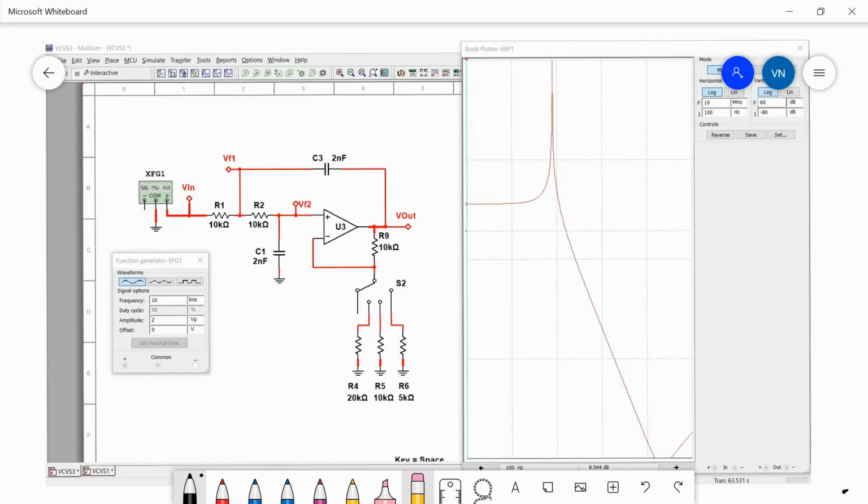Now, there isn't going to be every circuit in there. Let's say this one here, where you have equal value components of R and C. This is called an equal value voltage controlled voltage source. And those types of circuits will be in cookbooks, and they'll have ready-made formulas for you. So you can start with those and then modify it from there to get the filter that you desire.